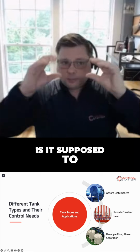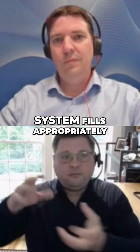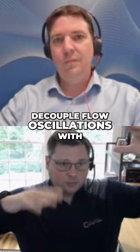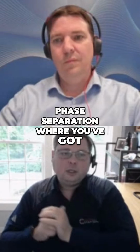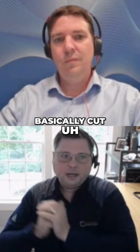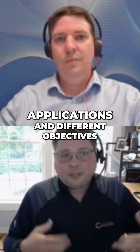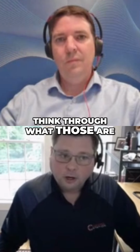Is it supposed to supply a very constant head pressure, so the system fills appropriately? Is it supposed to suppress disturbances? Is it supposed to decouple flow oscillations with the surge tank in the middle? Is it designed for phase separation, where you've got materials and circuits that are trying to basically cut a different phase in the fluids across a weir or something like that? All those are different applications and different objectives, and you need to think through what those are, right?